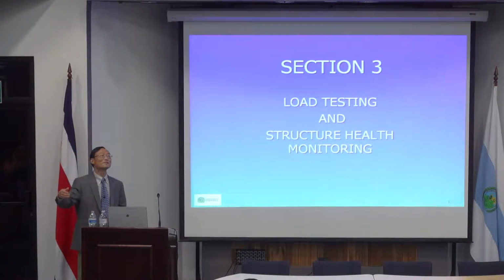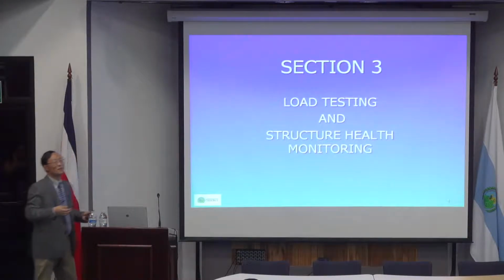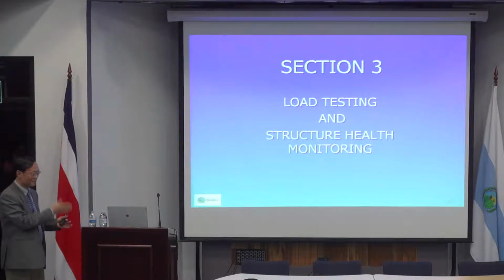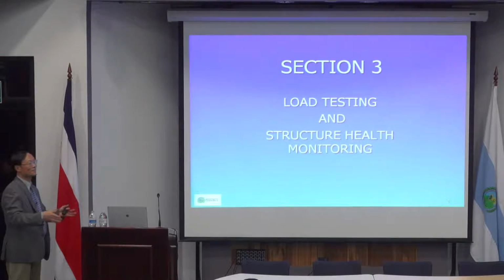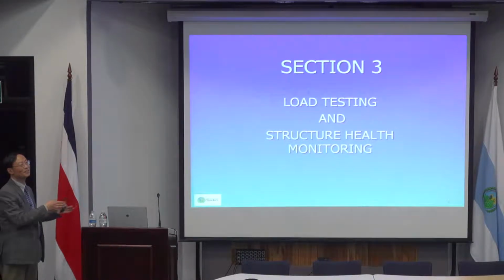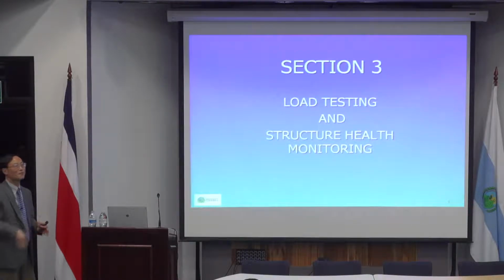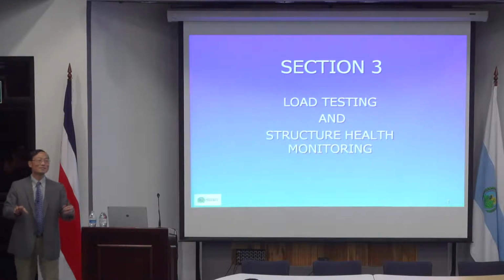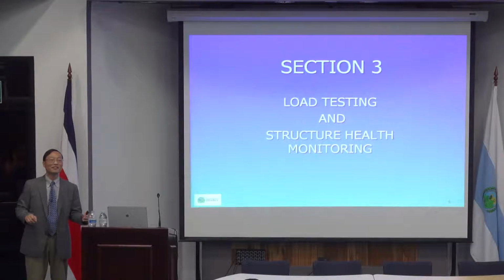And transversely typically you have diaphragm and the slab. Basically you assume you're cutting the slab into segments of, for example, 1 meter each. You have many transverse beams, and then you just put this into your model.